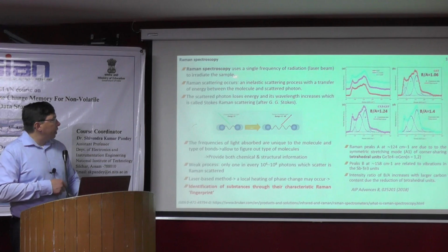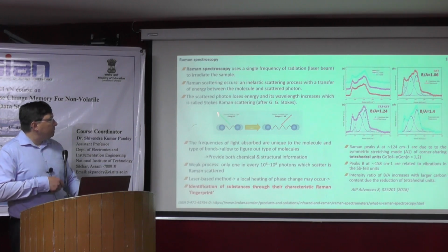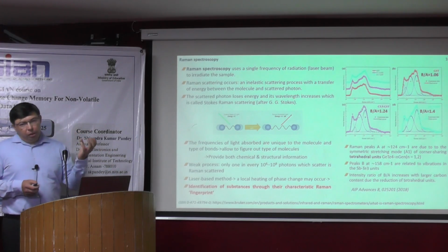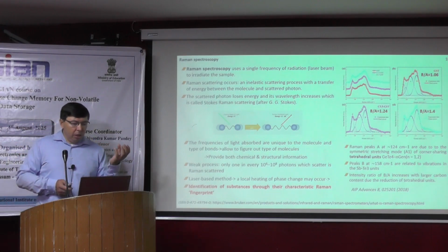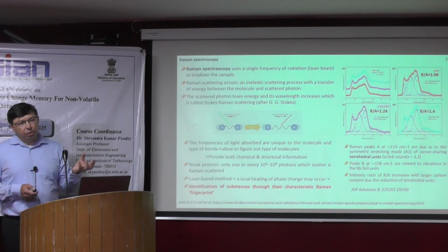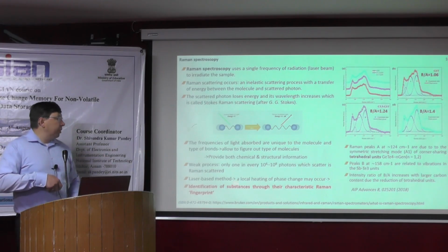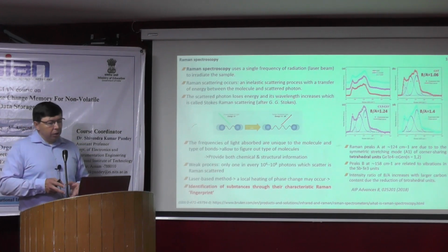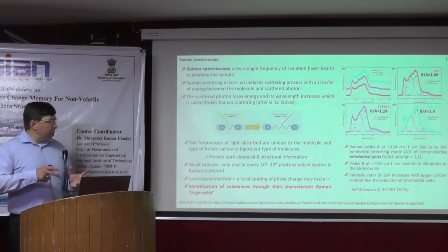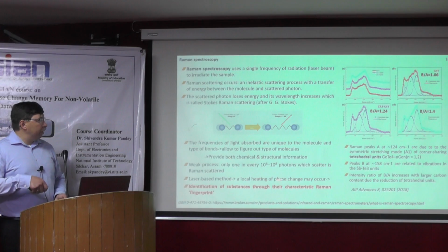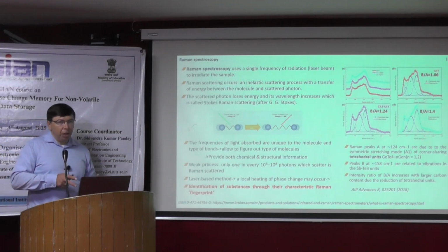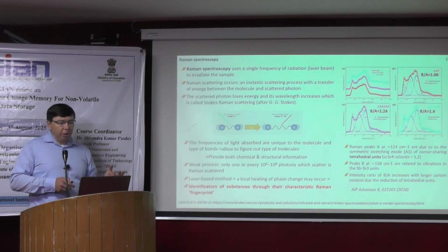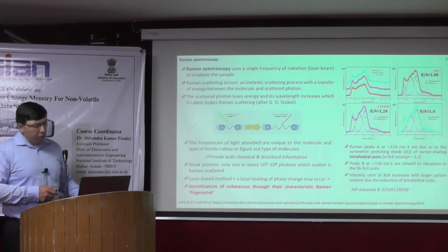And there is also one disadvantage of this technique. This is a laser-based method. You need a laser for the Raman method, and you know that in amorphous phase change materials you can induce crystallization by using a laser. So here you should play with different energies of your laser to find the optimum laser energy to study your amorphous materials. For crystalline materials, it may not be a big issue, but for amorphous materials you should be careful. You can induce crystallization of your amorphous materials and then study not really an amorphous solid.